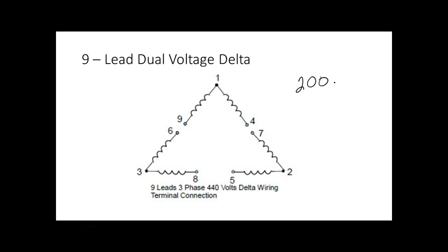What's the rule of thumb? 6 to 8 times, right? So that means a 200 horsepower motor, you put that thing across the line, that sucker could try to generate 1,200 horsepower or 1,600 horsepower. 1,600 horsepower could tear the gearbox up. It could tear things up, right?